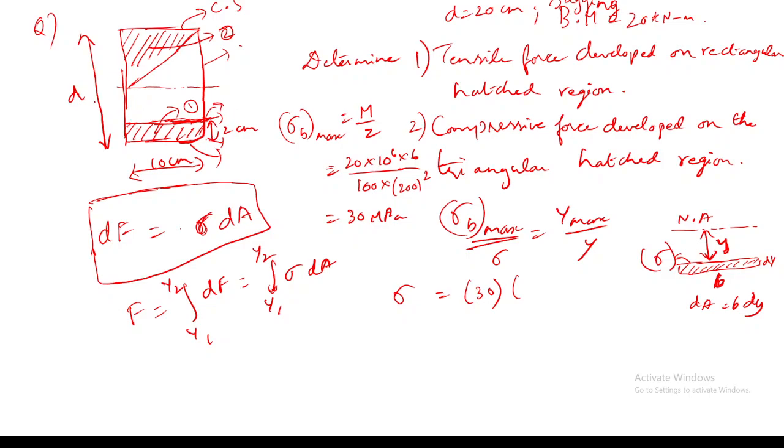The total depth is 20 centimeter, so half of this is 10 centimeter, and for this 2 centimeter alone I have to find out the tensile force. So y will be 8 and y max will be 10. So this will turn out to be 24 megapascal.